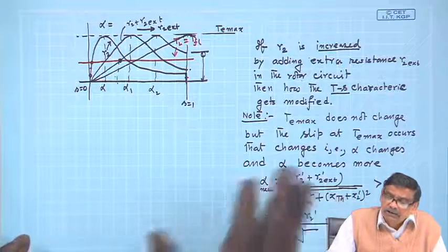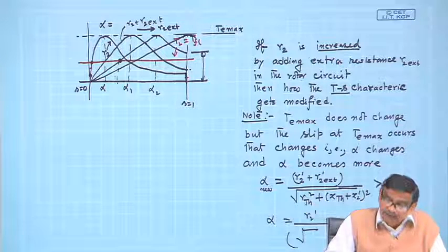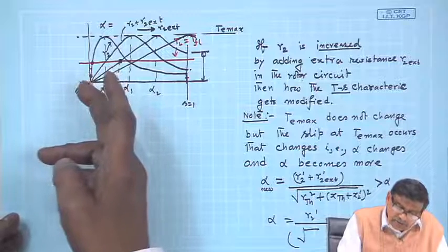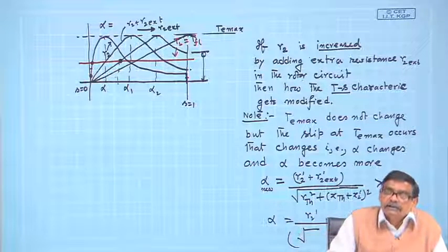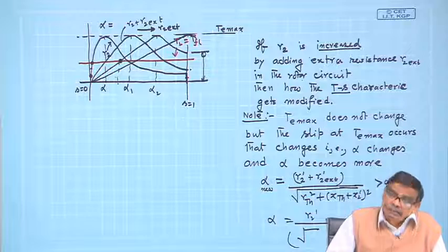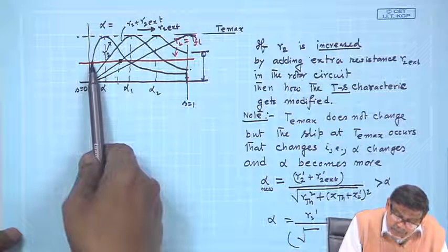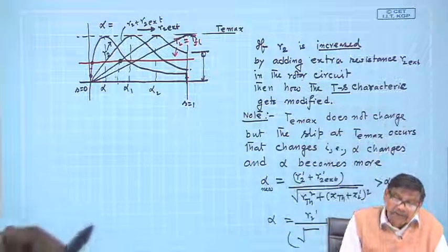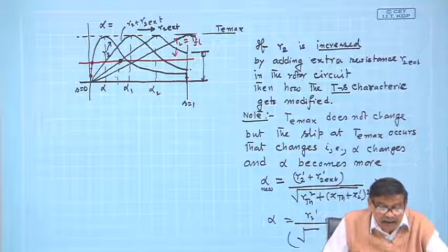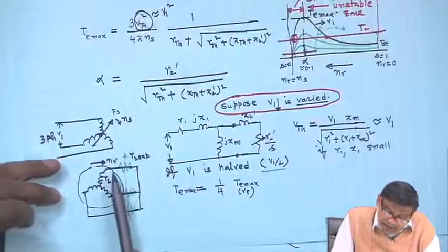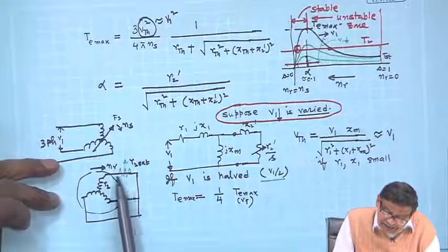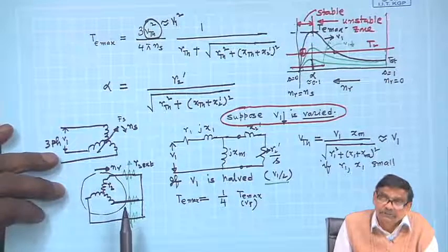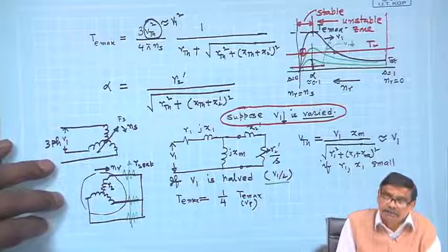Keep the rotor shorted right at its terminals, and after the machine settles down to no load speed, put that opposing load torque on the shaft, and then the machine will operate here. But I am now telling another interesting thing. If the rotor terminals are available, I will connect some R2 external, this green external resistance, of equal values so that the balance is preserved.